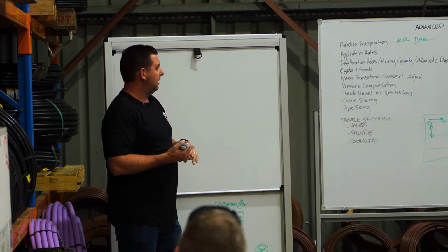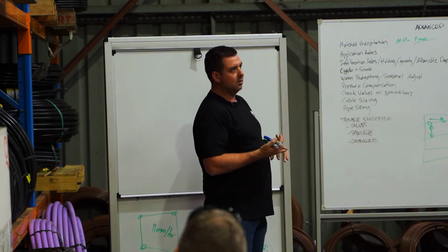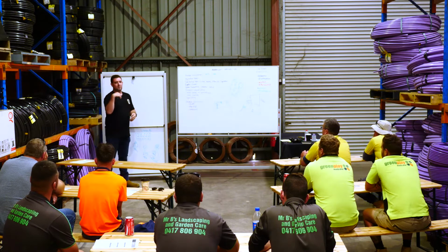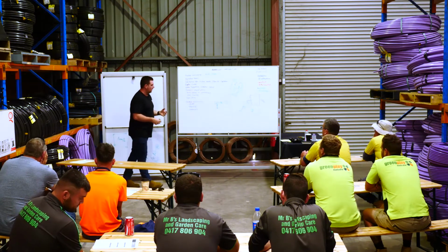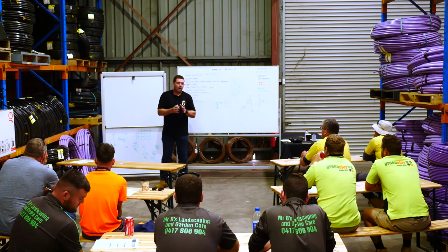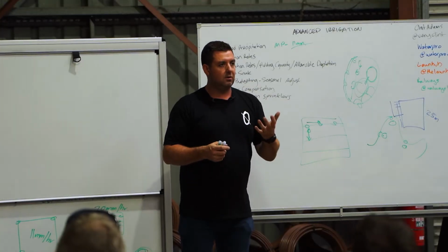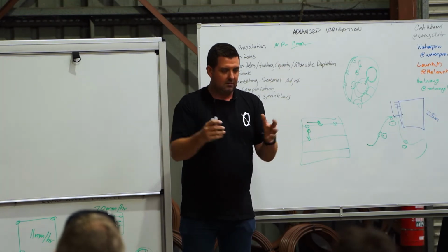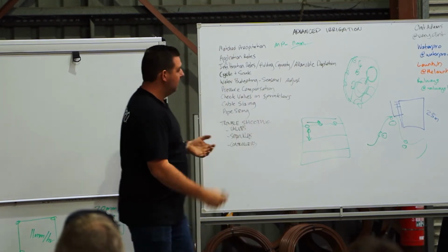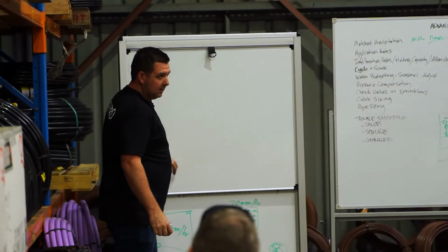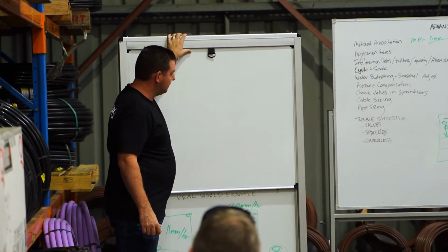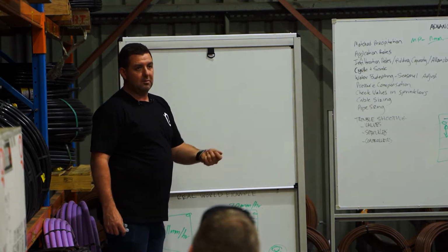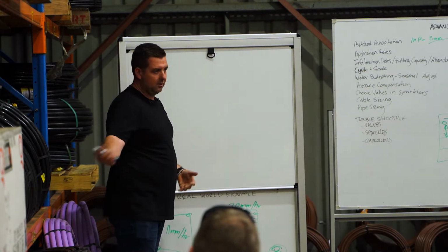So you would have seen in irrigation controllers, you've got program A, program B, program C, program D, 4 start times, however many stations, and it gets quite complicated. With the introduction of Wi-Fi controllers, it's made it a lot easier for you to sit down in a more comfortable situation than a shed with spider webs and darkness, and plan your scheduling. If you can plan your scheduling before you get to the point where you need to do it, you're going to do a better job. With Wi-Fi controllers, if you do make a mistake, you can easily fix it from back at the office or your mobile phone.